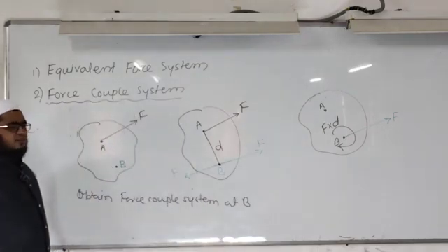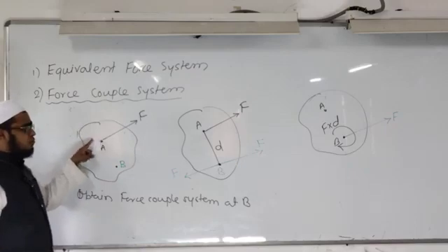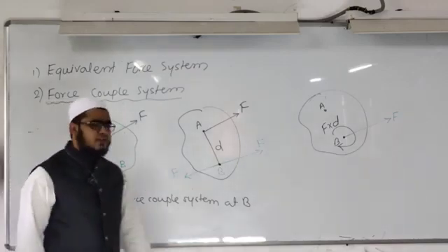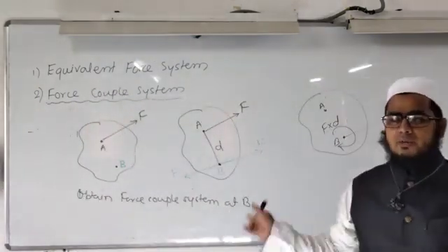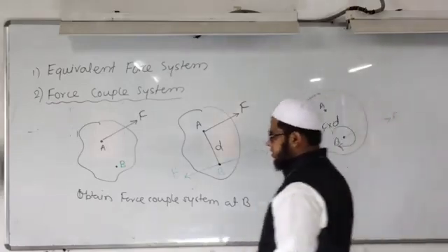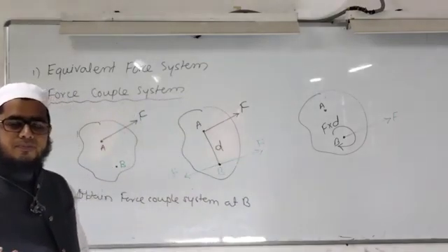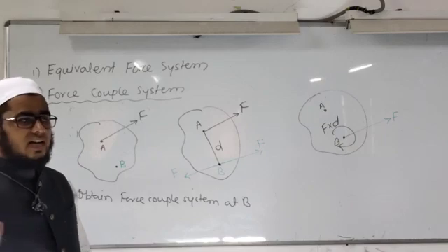Whenever the force couple system is required to be found at a particular desired point, transfer the given single force. I will explain the steps to obtain the force couple system. Transfer the given single force to the desired point with the same magnitude and direction.